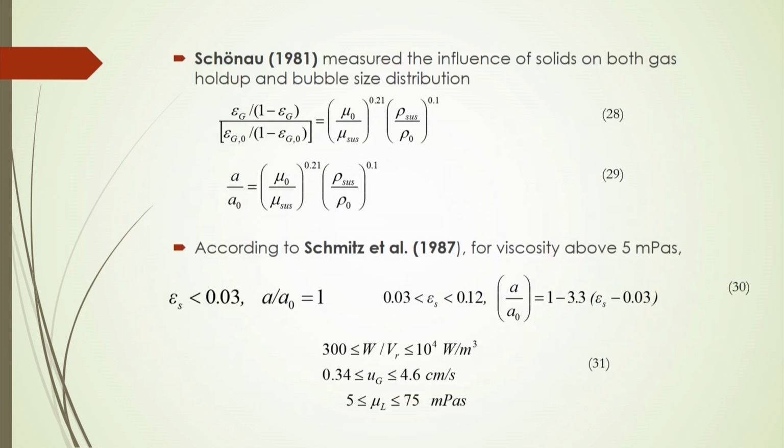And in 1981 they measured the influence of solids on both gas hold-up and bubble size distribution, and developed respective correlations as given in equations 28 and 29.